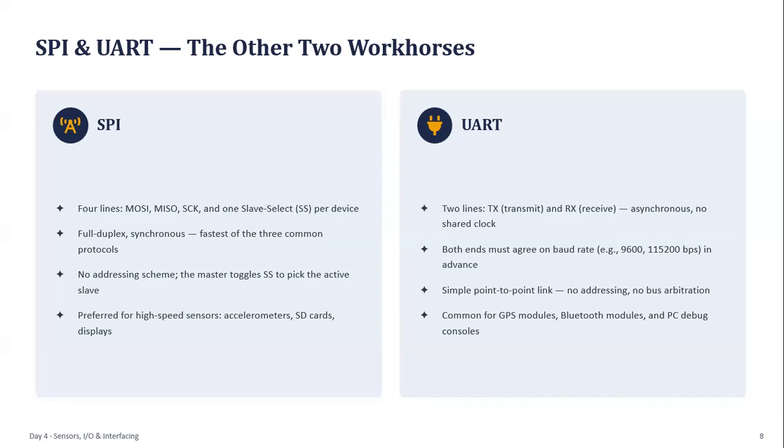Universal asynchronous receiver transmitter uses only transmit and receive lines. Both communicating devices must operate at the same baud rate. UART, Universal Asynchronous Receiver Transmitter, is the most simple, highly reliable, and extensively used in embedded systems, debugging, and wireless communication modules.